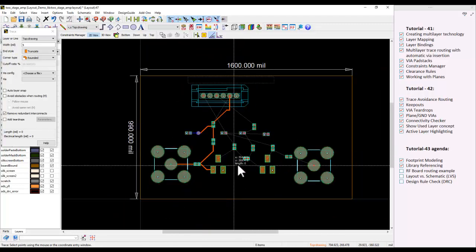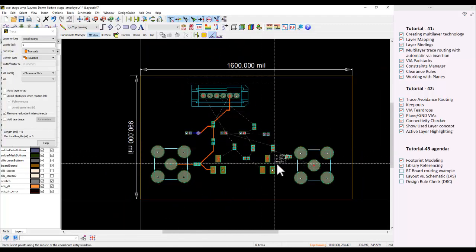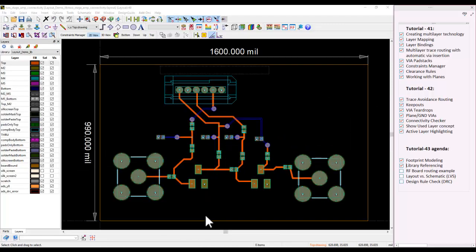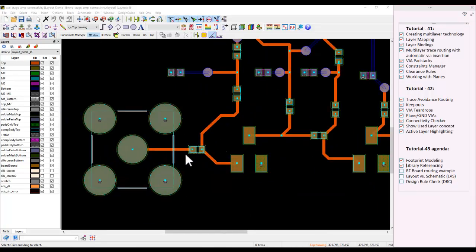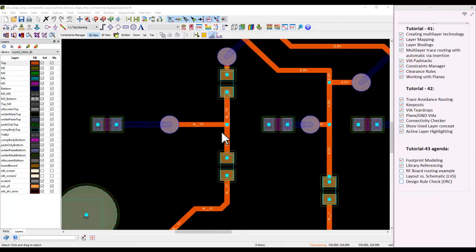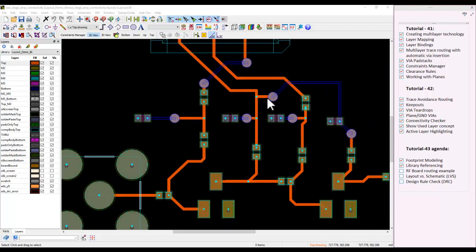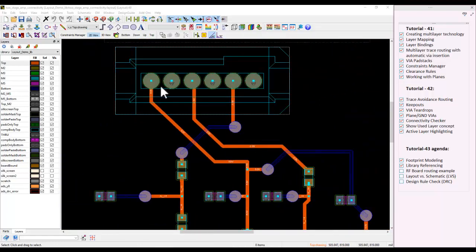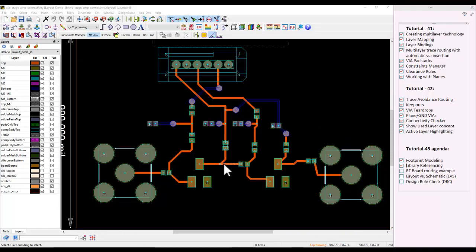So it's pretty simple. This way, I will again pause the video and I will finish all the routing to show you the end result. All right, so by spending 2-3 minutes, I already routed the board, and you can see it's not a very complicated board here. And again, I made this connection at the center point, and that's where it accepted the connection, because if you're not at the center of the trace, the connectivity is not completed. And again, wherever I have to switch the layer, I have switched the layer, and then I have made all those connections as needed in the schematic.